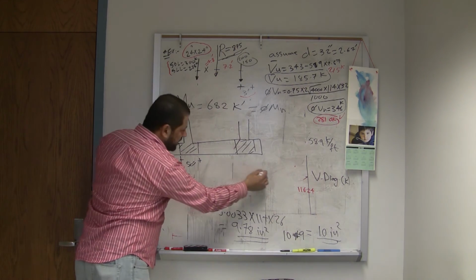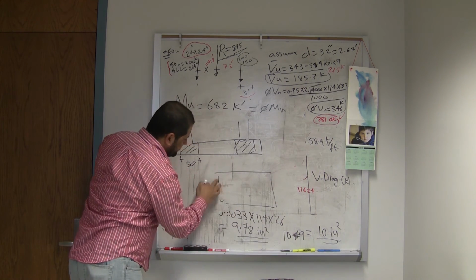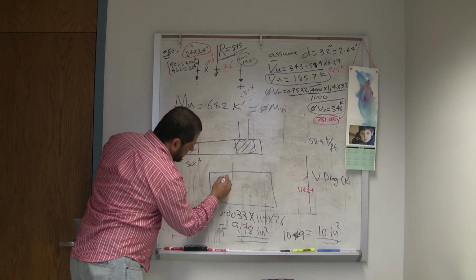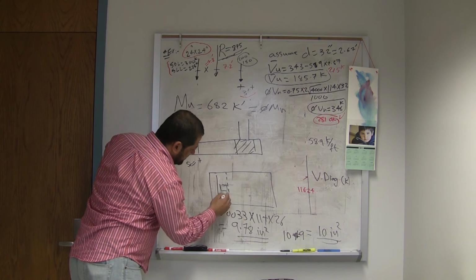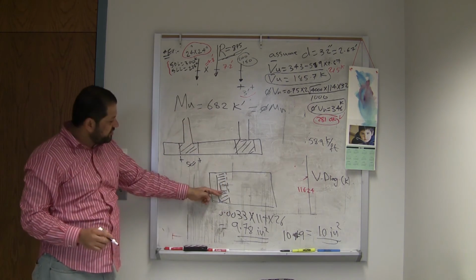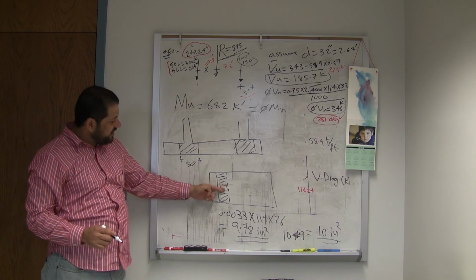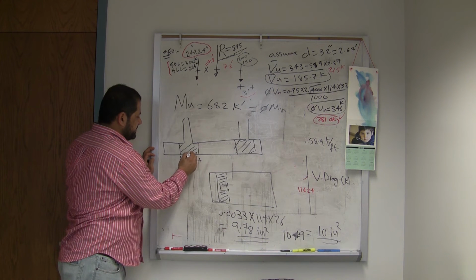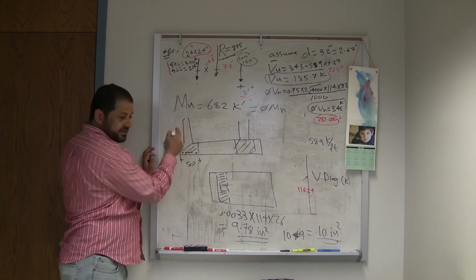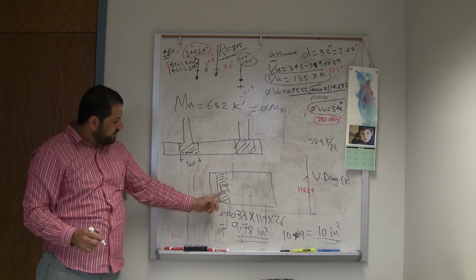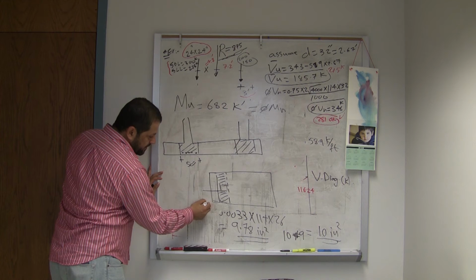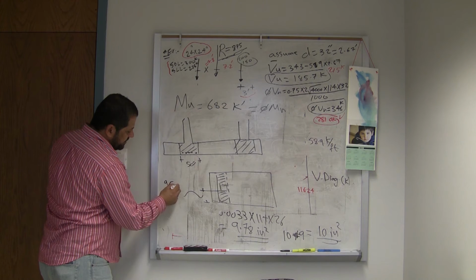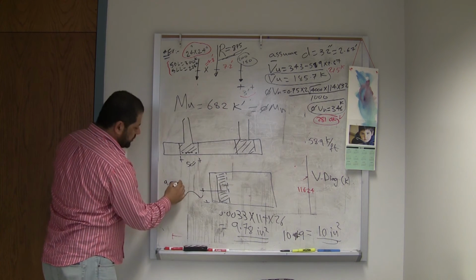We assume this beam, if you look at the plan view, that's your column. This beam is supposed to act as a cantilever at the face of the column. So there will be reinforcement at the bottom in here, special reinforcement in the other direction to resist this. The arm for that, this cantilever arm, will be 9.5 minus 2 divided by 2.